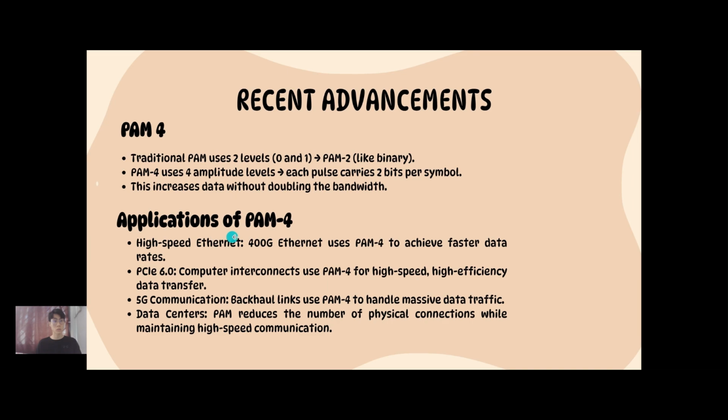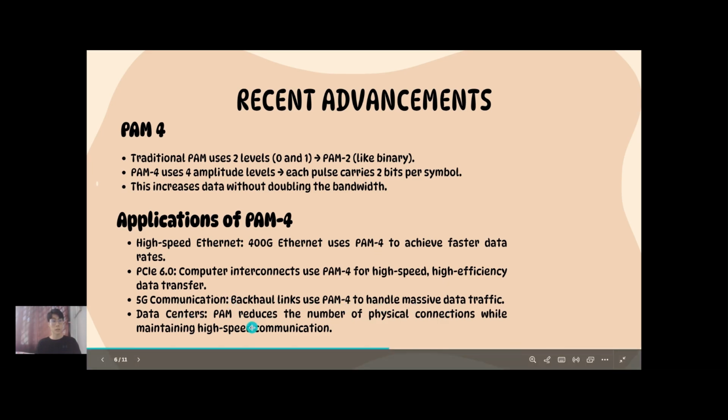Now I'll move to the applications of PAM4. High-speed Ethernet: 400G Ethernet uses PAM4 to achieve faster data rates. PCIe 6.0: this is the latest version of connection in the computer. It connects the CPU, GPU, RAM, and Wi-Fi with other hardware, and allows faster transfer of data between the components. 5G communication: backhaul links use PAM4 to handle massive data traffic. Data centers: PAM reduces the number of physical connections while maintaining high-speed communication.